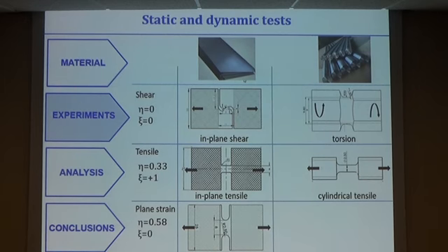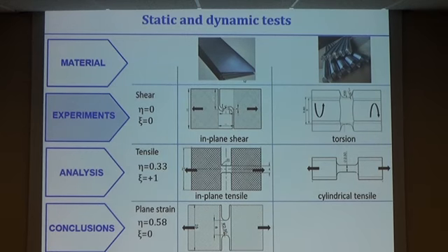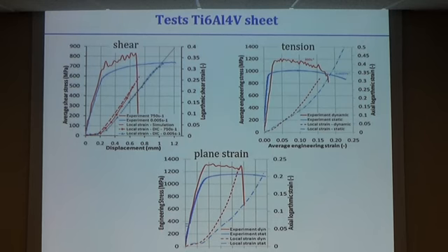Then also a very classical tensile experiment, of course a small tensile experiment, and then we also have the plane strain experiment. So, as you can see, different values of the triaxiality, different values also of the loading angle. For the extruded bar material, we carried out torsion experiments on thin wall tubes, also torsion combined with a certain level of compression, aiming at negative triaxialities, and next to that we also did the classical experiments on dog-bone-shaped samples.